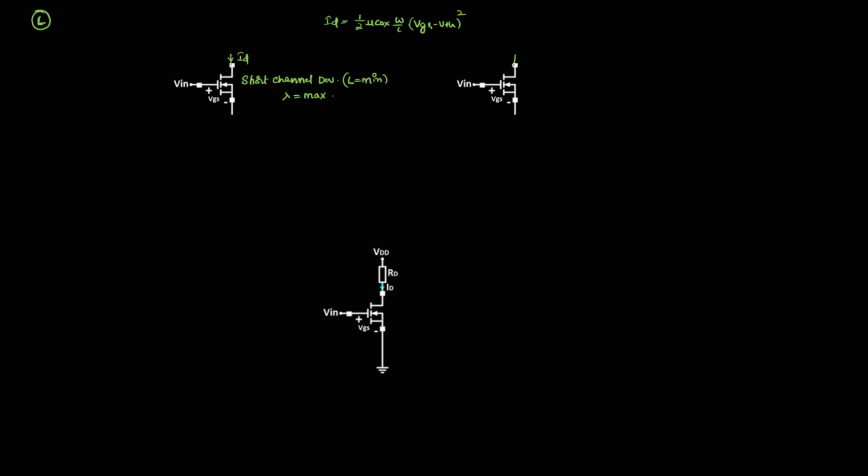It will be conducting the current of that much when the gate has total control. So whatever gate voltage we are applying over here itself controls the total flow of the current. This is the channel where the current ID has to be conducted. If the current ID is controlled totally by the gate, then the current equation is this one.